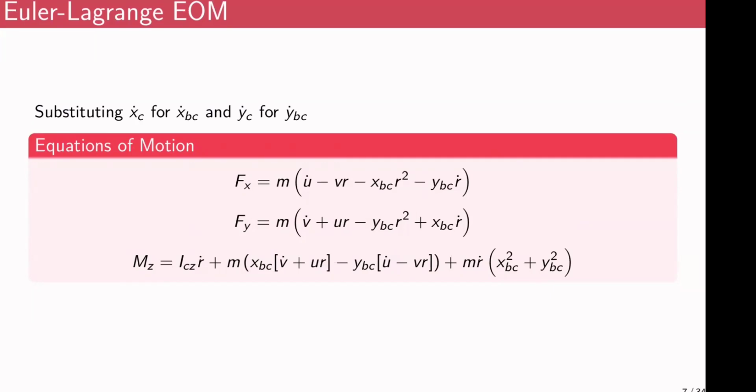But the difference in formulation becomes much more relevant in manipulators, right? In manipulators, the Euler-Lagrange method would only give you the joint torques, but the Newton-Euler method gives you much more comprehensive insights. Apart from the torques, it will give you the reaction forces in all the other directions. Right. So that is really useful if you are designing the links of the mechanism. Right. So only one component would be counted as the actuation force.